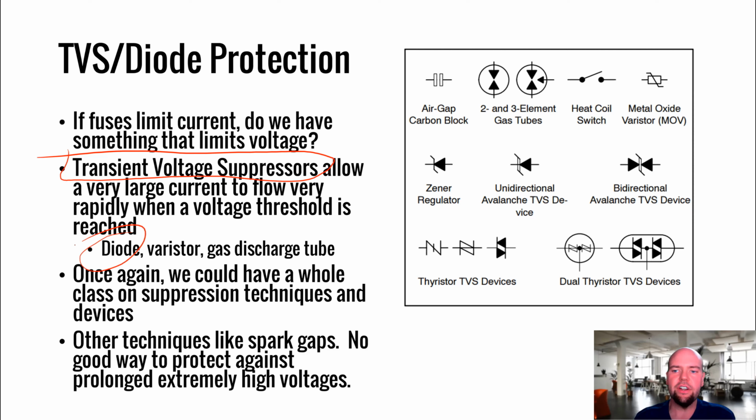These are diodes designed so that when the reverse voltage across the diode gets high enough, it causes a massive amount of current to flow. The thought process is, if you're over voltage for a little bit of time, the thing that's causing the overvoltage event probably can't provide both a massive voltage and a massive current.